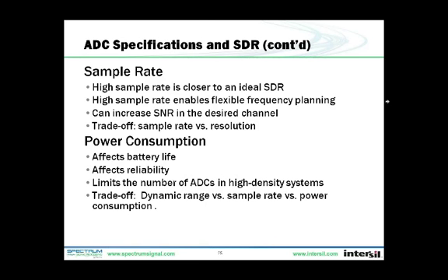The amount of power that the ADC draws will also impact your SDR system performance. It affects battery life in portable applications, and it affects reliability as the higher power consumption results in a higher temperature, and the ADC is often one of the hotter components on your board. It also limits the number of ADCs that you can accommodate in high-density systems with multiple ADCs. There's a trade-off between dynamic range, sample rate, and power consumption. A higher dynamic range and sample rate also often mean a higher power consumption. Life's full of compromises.